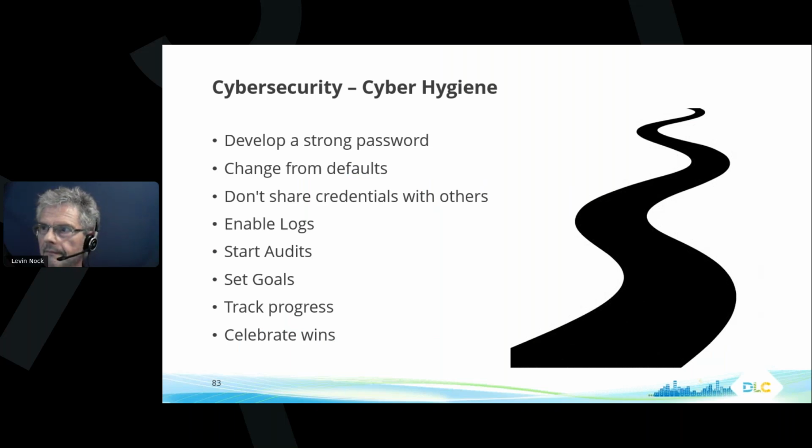So, obviously, make a good password, make a strong password, right? You may have an account where you are given default credentials, right? Change it from the default credentials immediately. Whenever you get a controller online in a project, change those default credentials that come from the factory immediately as soon as you start working on the job, right? Don't share credentials with others. Have credentials specific for each user that needs to log into the system, right?